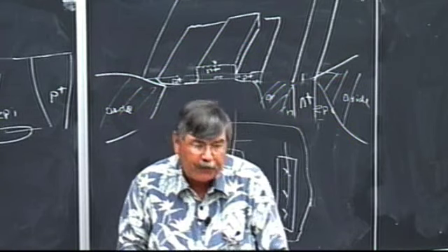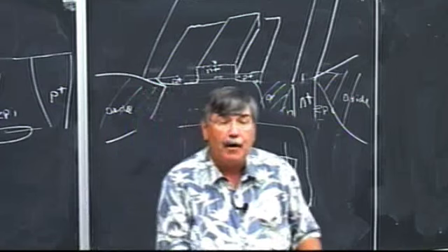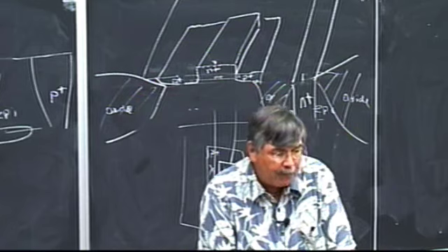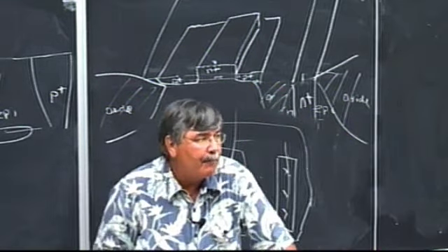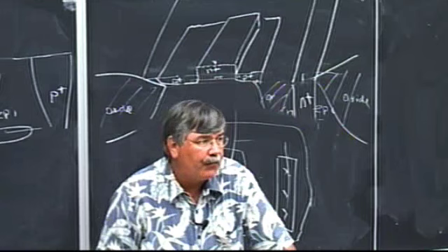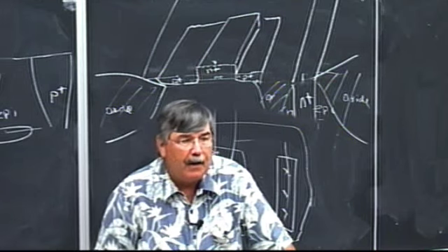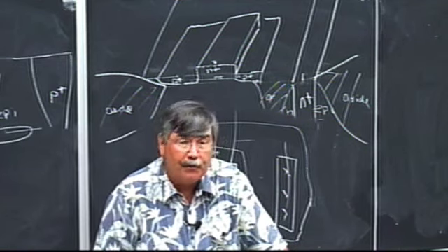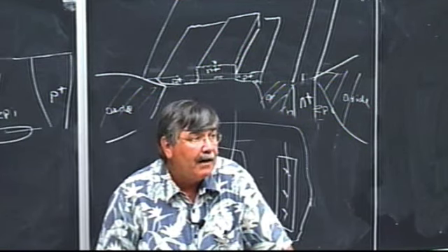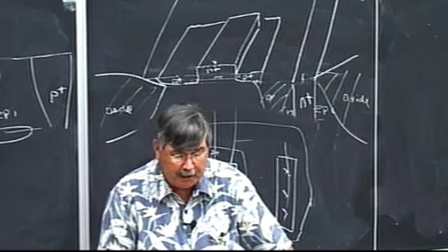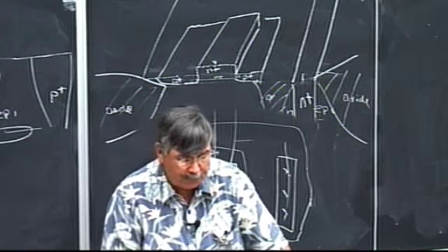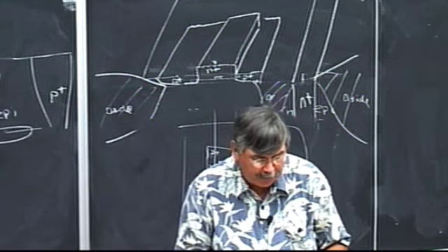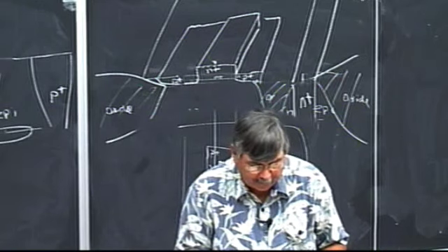These days, most of the technologies are optimized for building CMOS, complementary MOSFETs on there. There's some stuff in the notes about how that would go. So these processes where you just have NPN bipolar transistors, there's not very many of those at all. There are some really sophisticated processes designed for people like us that are designing good analog circuits where they have not only good vertical NPNs, but vertical PNP transistors. And we need to talk a little bit about that. And there are some very nice processes these days that use a few other tricks.